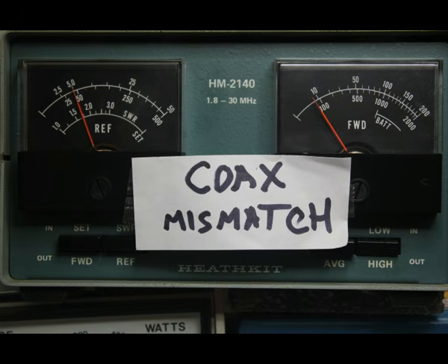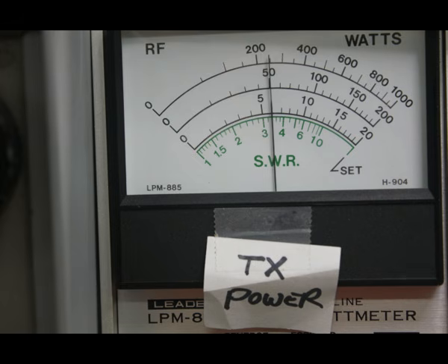But I'm going to give you a little tip when you're reading power on a power meter that's a directional coupler type and it's not in the line impedance that it's designed to operate in. What you can do is subtract the reflected power the meter is showing you from the forward power you see on the meter. The reflected reading isn't really power flowing backwards. It's just an artifact of what the meter's doing.